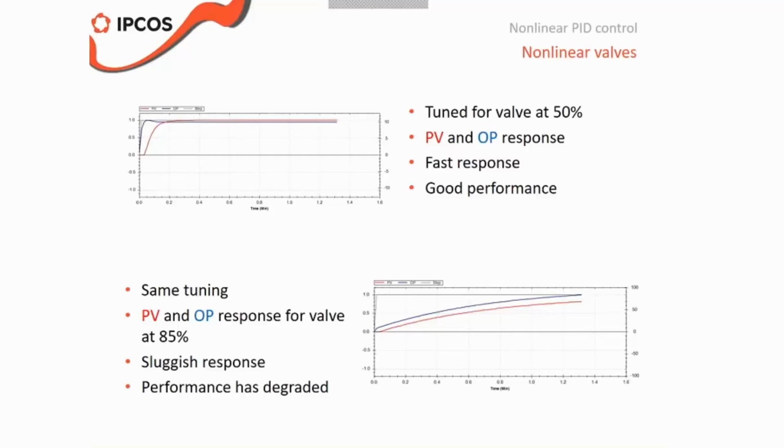That means that whenever the unit is hit by a disturbance, it takes longer to go back to normal operation again. And that can be a bad thing, definitely if it is, like I was saying before, a temperature controller on an exothermic reaction. You definitely want to maintain the temperature even if some disturbance hits the plant. And this is for a flow controller.